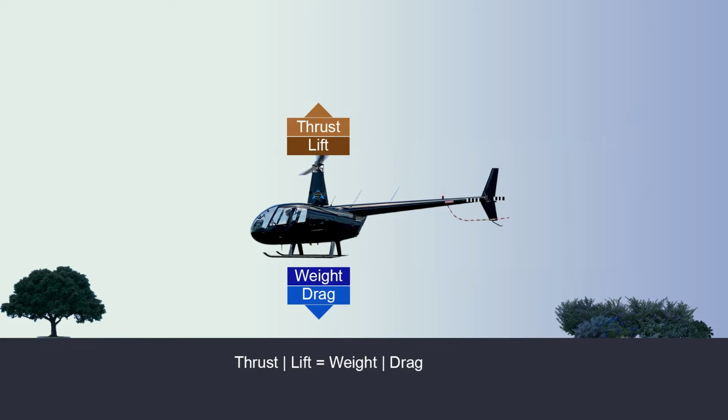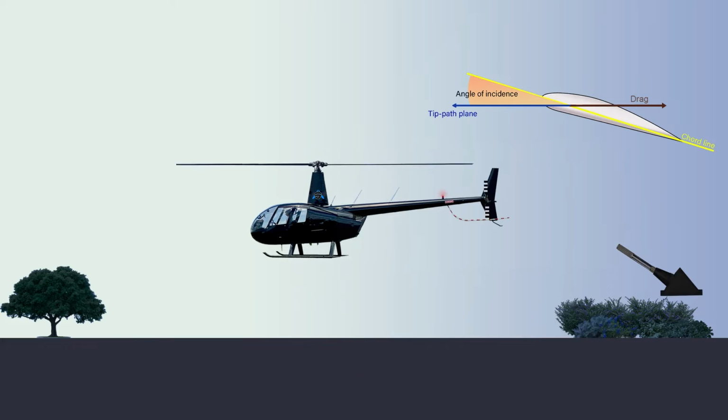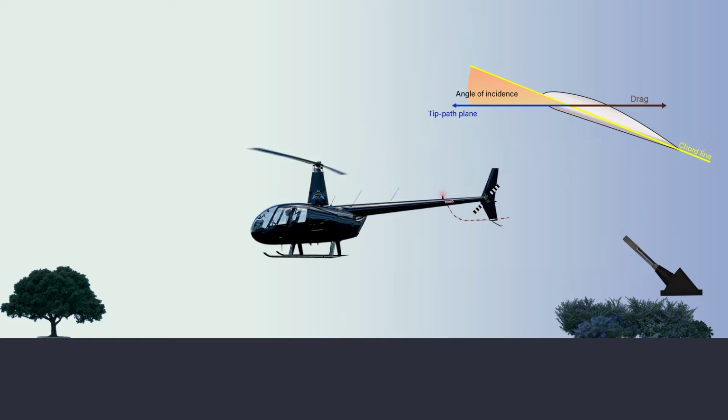While hovering, the amount of main rotor thrust can be changed to maintain the desired hovering altitude. This is done by changing the angle of incidence of the rotor blades and hence the AOA of the main rotor blades. Changing the AOA changes the drag on the rotor blades, and the power delivered by the engine must change as well to keep the rotor speed constant.